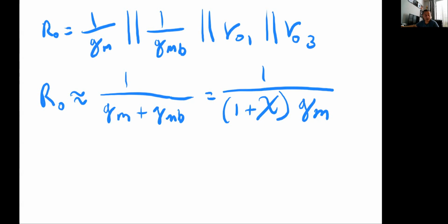But there are better current mirrors with better accuracy, with higher output resistance, which is a desirable thing. Lower voltage operation is another desirable characteristic, because, as we discussed at the beginning of the chapter, with smaller transistors and thinner gate oxides, the voltage range keeps getting smaller, so you start operating very close to the threshold. Some of that is explained towards the end of the chapter.